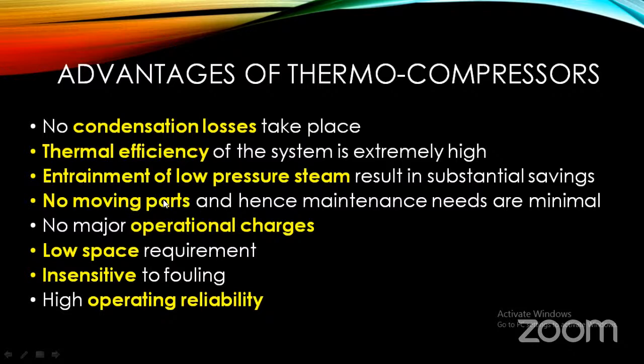And since the pressure conversion happens in the nozzle, operational charges will not be a major one. Low space is needed because it's a simple nozzle and diffuser form only. Fouling will be lesser, and thereby, if you combine everything, the operating reliability will be higher.